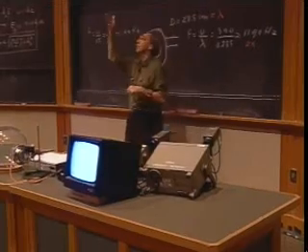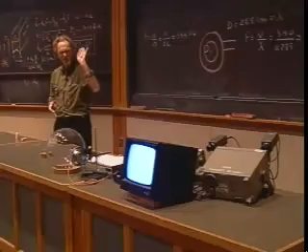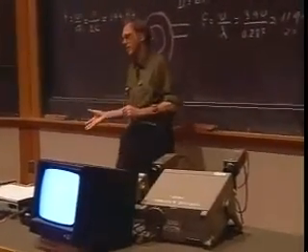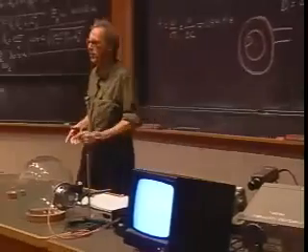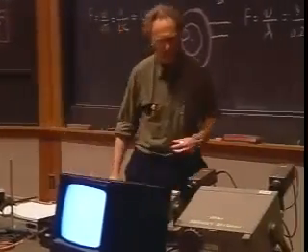Well, we were staring at each other in disbelief, and so we went on. I said to him, you know the 60 hertz are the lights in the building. That's what you pick up. It's some pickup, some crazy pickup. It's not a sound resonance. Whenever you see 60 hertz in the United States, or 50 hertz in Europe, you know it is some pickup. So I was willing to forget about it.